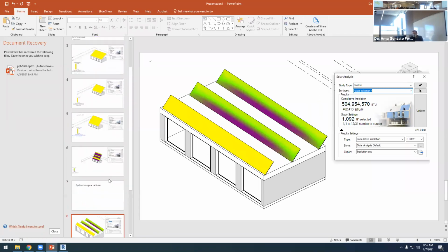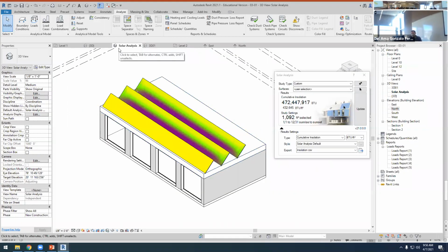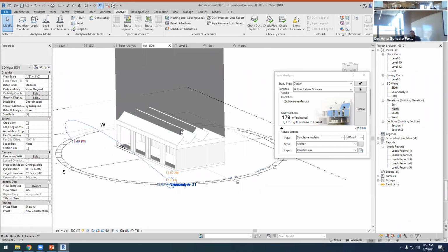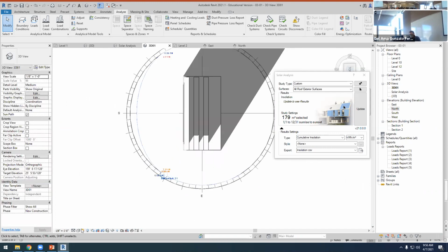Okay. Is it easy? Well, if you have done this thousands of times, you know what the best solution is. So you don't have to ask, okay, what is the latitude? 42. Okay, what is the optimum angle? Around 40. Let's do that. So you don't have to think about it. Then the distance. I would always use Revit to analyze the sun or the shadow analysis.